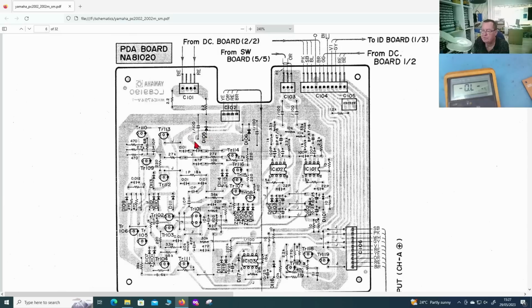If we look at the same components on the layout, we can see here, this is where the power was coming in, that's the yellow light going back out. We have these two components. Again, we can look around this track, put anything like, for example, a shorted diode there, wouldn't have a path to ground. It is this one. This is ground. So both of these components basically connect via this wire J to the end of this connector.